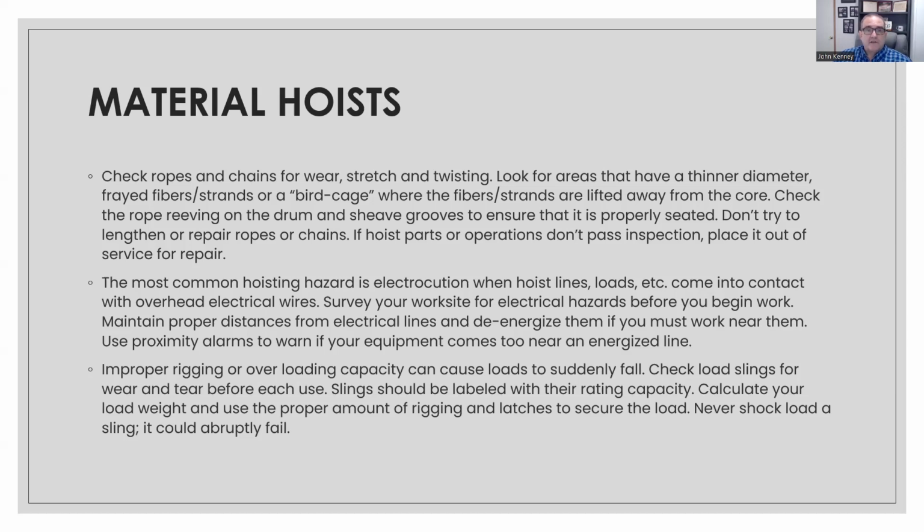The most common hoisting hazard is electrocution, when hoist lines or loads come in contact with overhead electrical wires. So again, you want to make sure you're surveying your work site for electrical hazards before you begin work. You've got to maintain the proper distances from electrical lines and de-energize them if you must when you work near them.